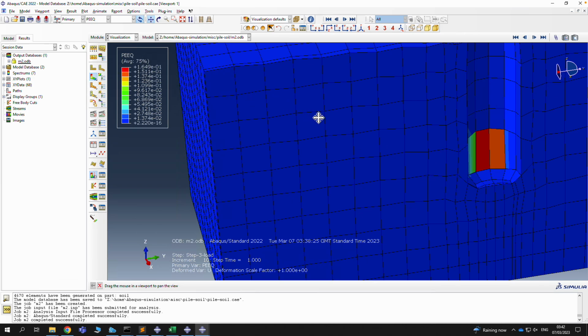A plastic strain of 0.1 is significant. But to model this localized plasticity, we should use a more refined region around here, and in that way we can correctly simulate the stress localization and plasticity calculation. But I am not going to do that. This could be a task for your project.